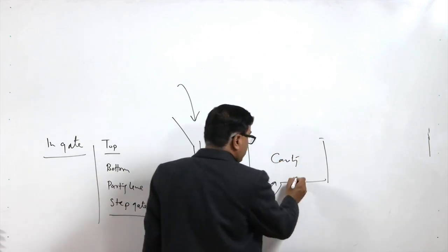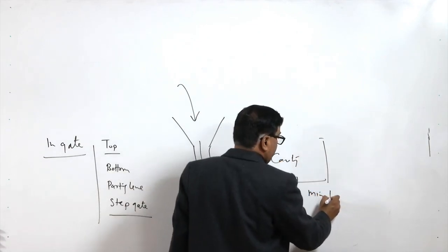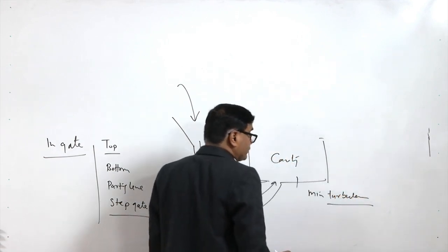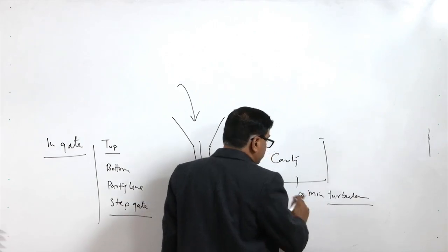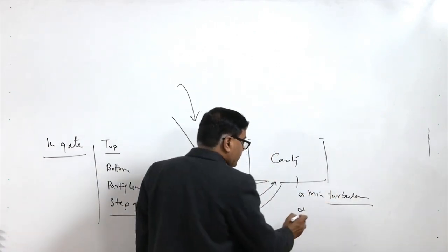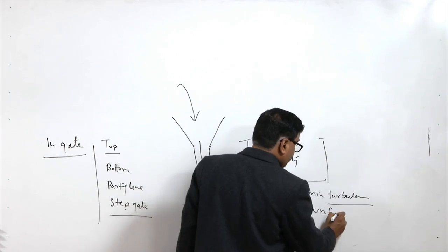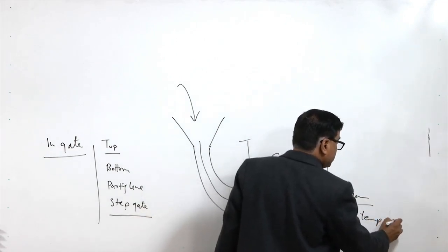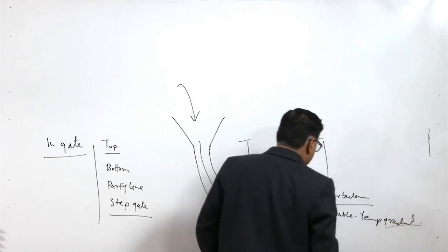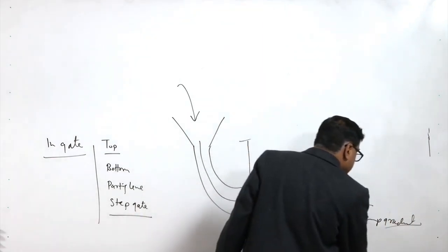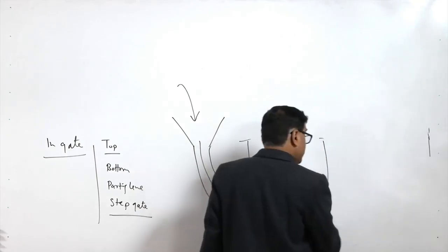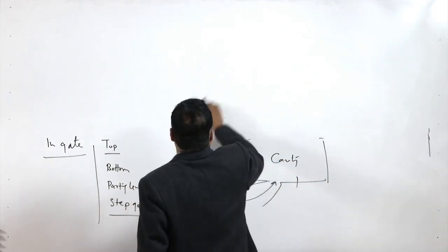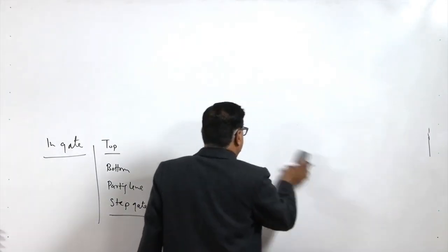The good part is there is minimum disturbance or turbulence to the molten metal, and no erosion, but the only problem is that it leads to an unfavorable temperature gradient. In this case it is difficult to realize the directional solidification, and it may lead to internal defects like the shrinkage cavity in the mold.